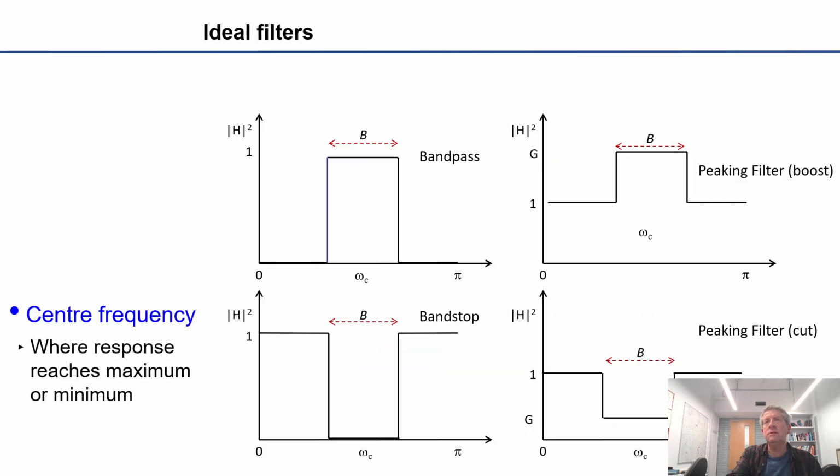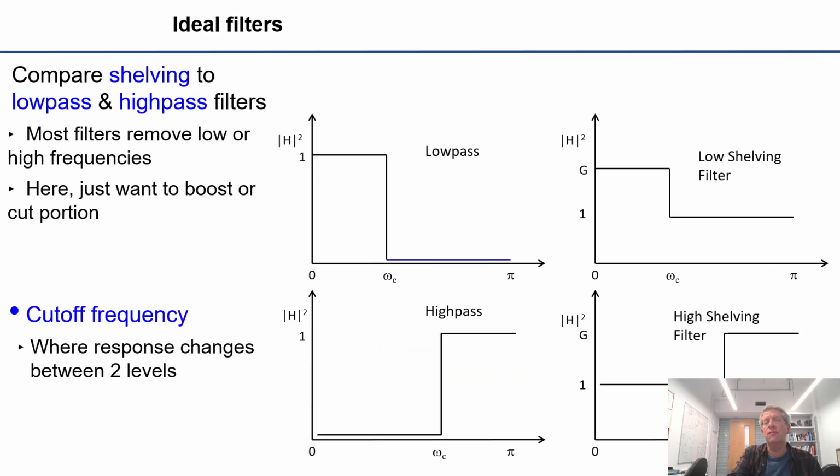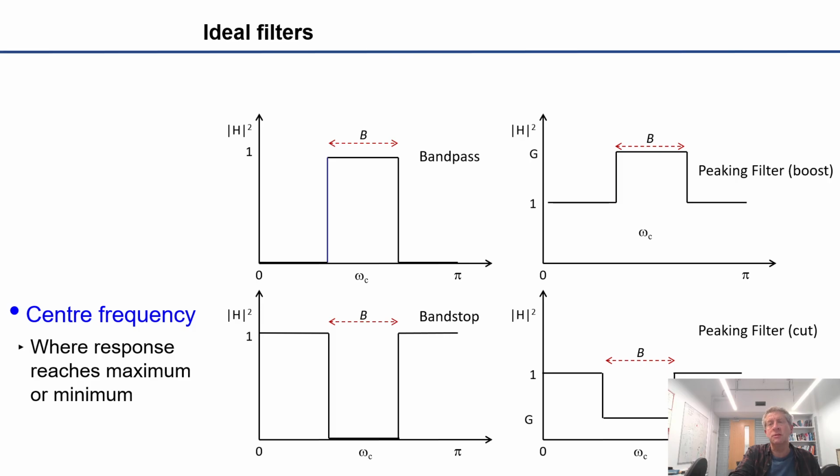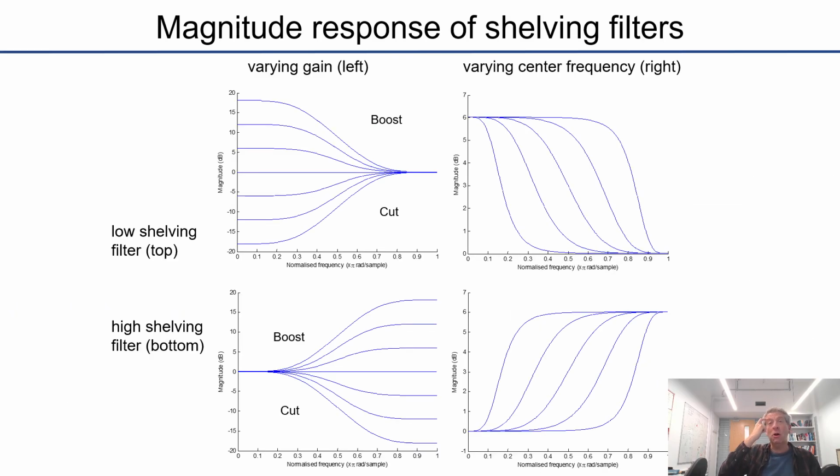So in the plots that were just shown, those are all sort of the ideal exaggerated behavior where, for instance, it's perfectly keeping all the low frequencies and then suddenly removing all the high frequencies. Much more common is smoother filter designs where there's a region of transition, and it can be a very slow transition from the response at high frequencies to low frequencies.